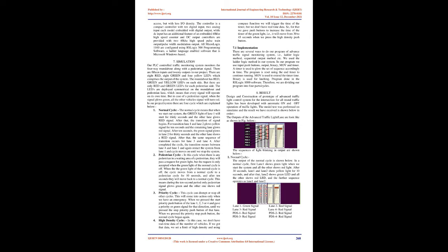6 Software. 6.1 Allen-Bradley Micrologix. The Allen-Bradley Micrologix 1100 family of programmable logic controllers, PLC, is also known as a small logic controller, especially for complete micro and small level automation applications. With data logging and relatively large allocated memory for resident storage as compared to Micrologix 1500, the Micrologix 1100 product line is excellent for remote monitoring and used for applications that require large and intensive memory access, but with less I/O density.